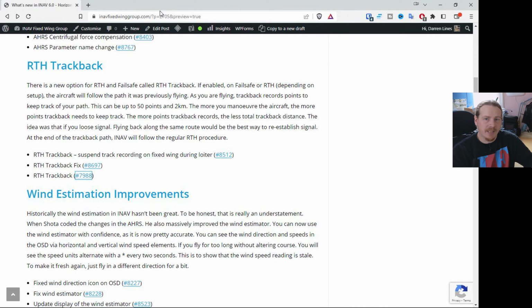There is of course a caveat. If you're flying a fixed wing, you still have to turn around. So there is that loiter radius which it will use to make that turn. If it doesn't get around that turn before it hits the obstacle, then unfortunately that's just bad luck, but there's nothing that can be done about that. But once it's made that turn, it will come back along that path.